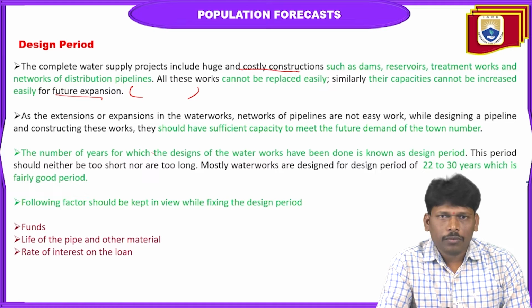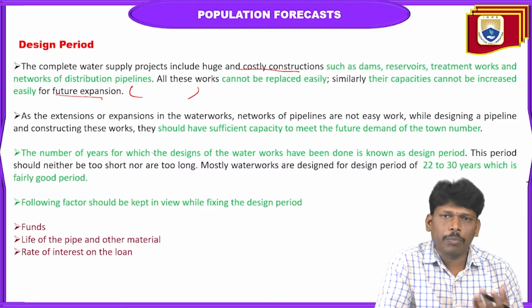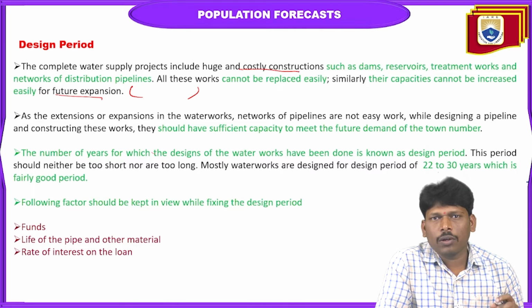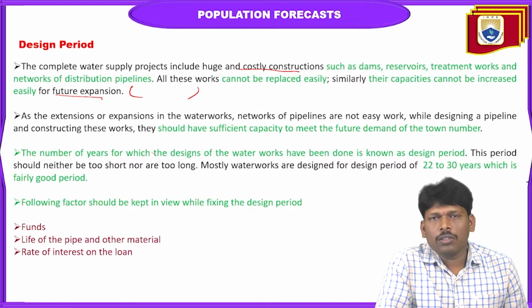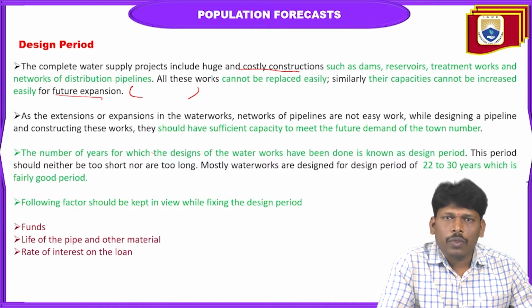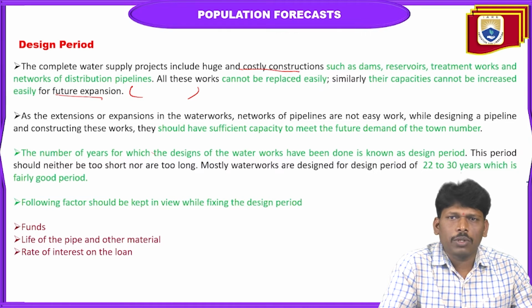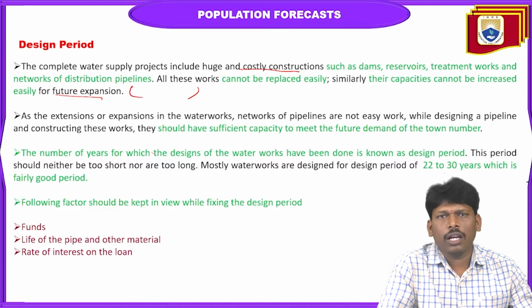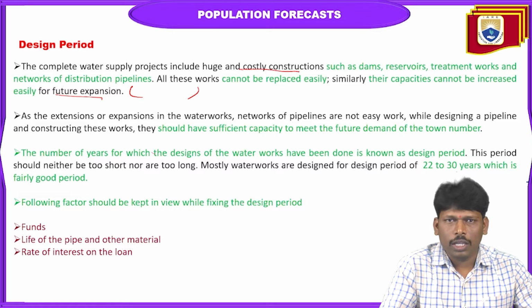So here it is very clear: while designing a dam, a reservoir, or pipelines, the designer or the persons involved in that particular work must have knowledge of how the population increases. And if it is a town, suppose you are supplying water to a metro city, in that case they must know the growth of urbanization and keep it in mind. They must also keep the industry growth and the population growth in mind while designing the pipelines and constructing water storage tanks and everything. Then the constructed elements can serve for 2 to 3 decades without any disturbance.